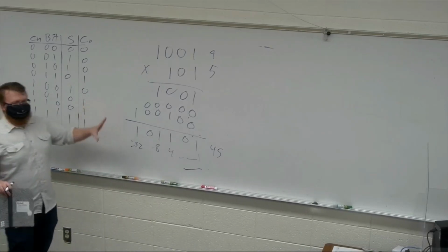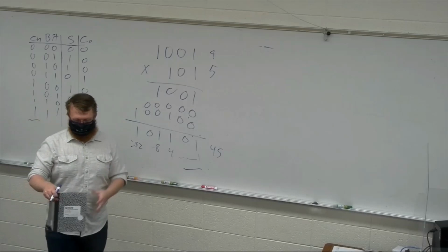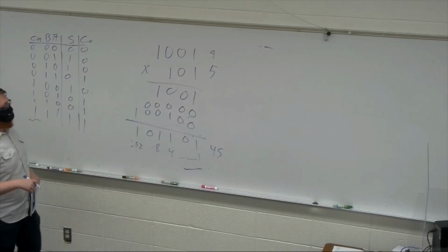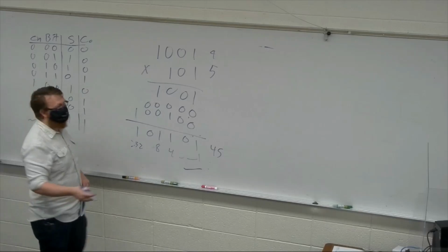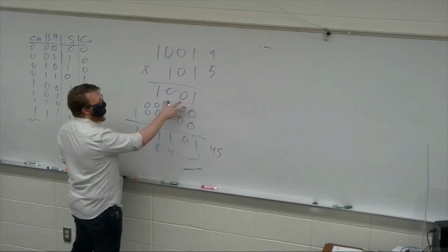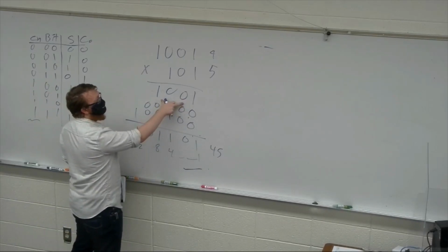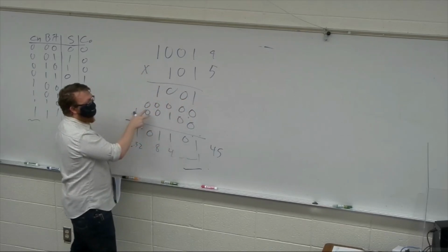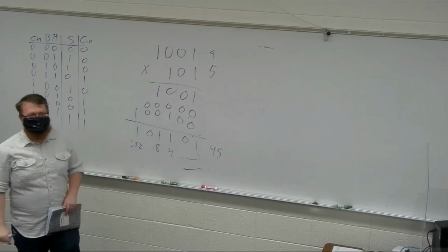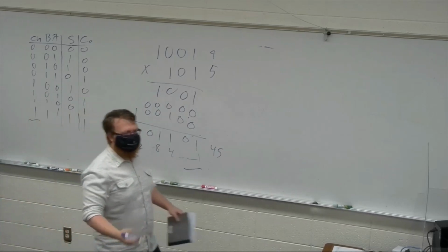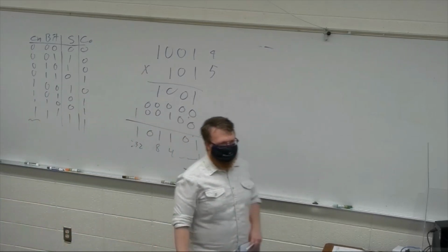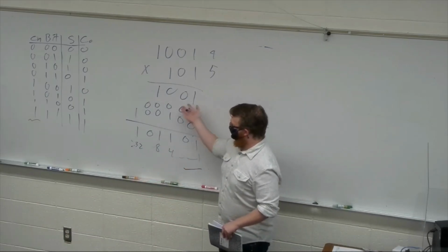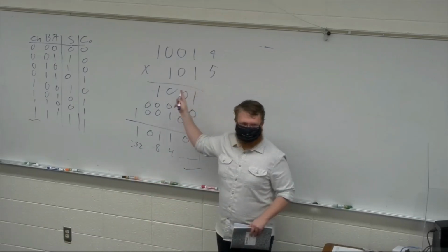Right, so that's multiplication. Now you're going to notice something. Well, maybe not, but this is what some very smart people notice: every time you do this, you're really just only ever taking the multiplicand and just moving it over if there's a 1. So this gave rise to what they call the shift and add method, where literally they just shift it and add it if there's a 1 here.